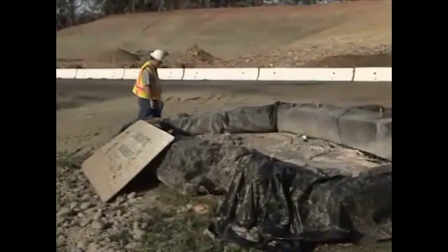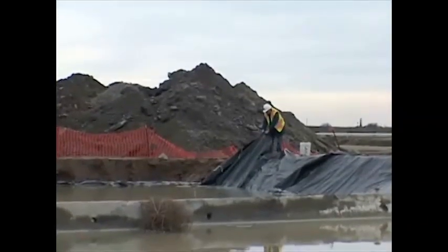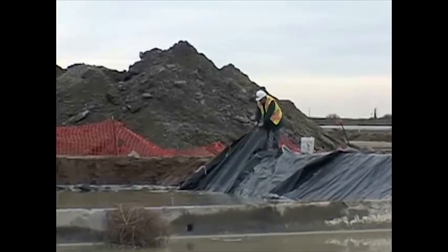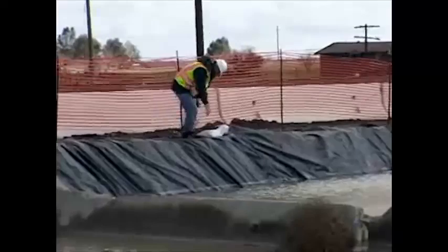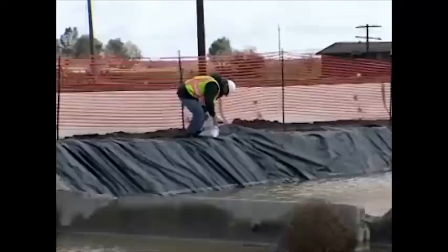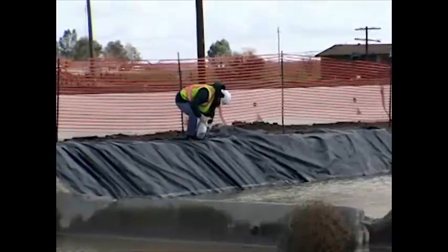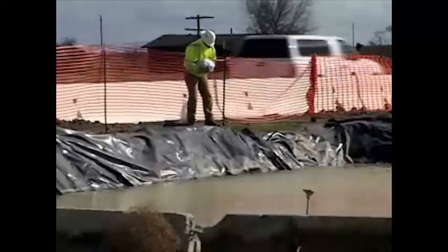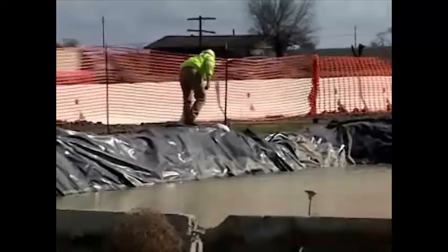The Water Pollution Control Manager should also check the liner for any type of damage, such as holes, rips, or voids in the lining. The gravel bag should also be inspected to determine if the bag material has ruptured or if the yarn has failed such that the bag contents spill out. Any damage noted during an inspection must be repaired immediately.